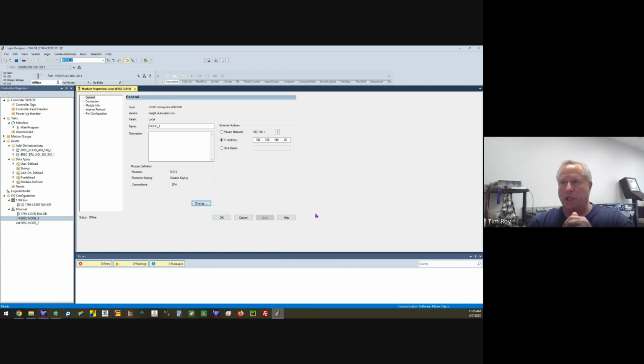If you go in and change the data type after you create it, some processors will, even though you went to an integer, keep data type A. Some processors will actually change it and upgrade it to data type G. I don't know what ranges, which processors, what versions, that I don't know. But I do know that if you delete it and recreate it, that will work for sure.